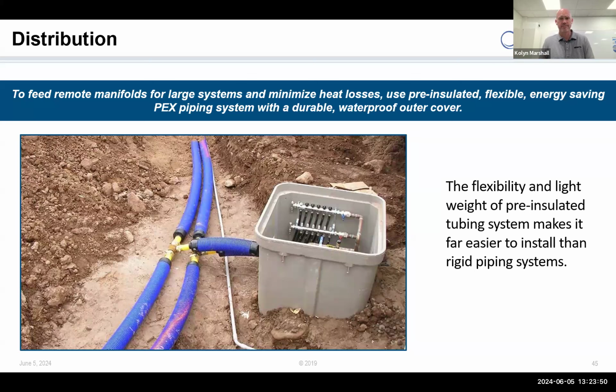So on the location side, obviously the picture you're showing there, it's very close to the loop. There's an application where someone's asking, it's for ramps for accessible areas. The manifolds are most likely located in the basement, lower than the loop. Are air pockets in the piping up at the high level loop going to be a concern? And I guess that ties into the venting that you were talking about, right? Yeah, so the answer is yes. Be aware of it. Is it a concern? No, but it is a factor. And there's actually two factors in that scenario. So I'll address the purging first.